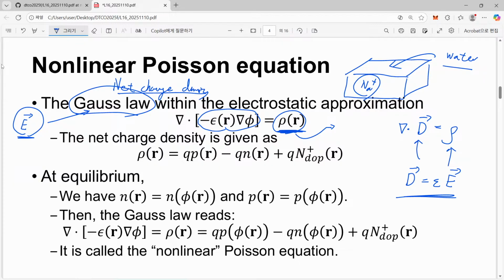So in general, there are many different ways to have a net charge density, but since we are talking about solid state semiconductor devices, there is no positive ion freely moving inside our system. All of our ions are just tied to the crystal structure. They cannot move. So although we can consider certain ionic charge from dopant, they should be regarded as just fixed.